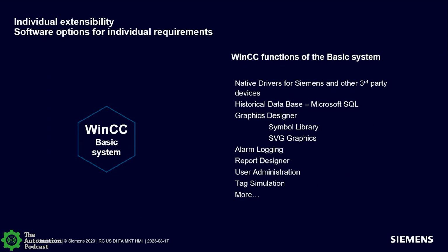Report designer, so you create some basic reporting there for end of shift needs or just other issues as you need them. Once again, for the security piece, there's a big user administration part where you can define tons of users and lots of different classes for the users. We've got the standard supervisor, operator, and a couple others like that, but you can create your own up to like 32 different user classes and assign them different rights for which ones I have access to within the project.